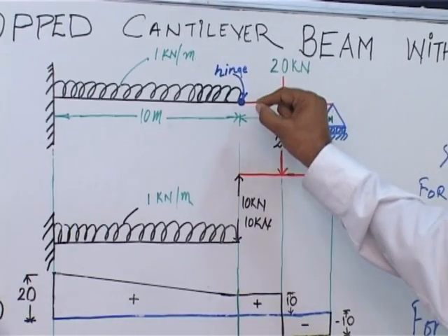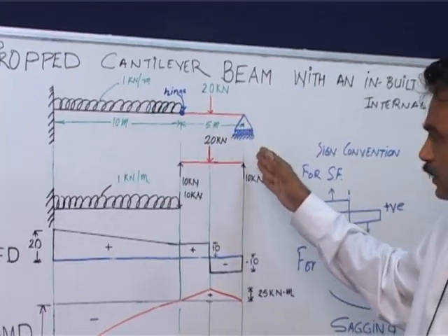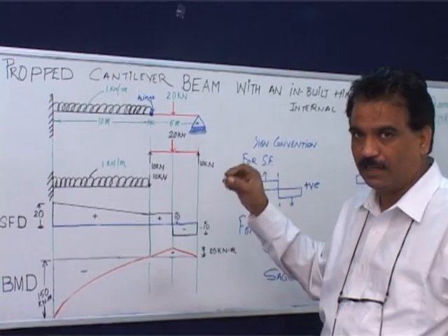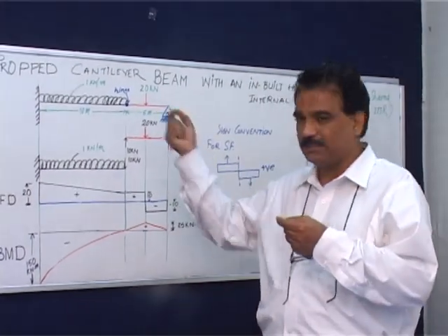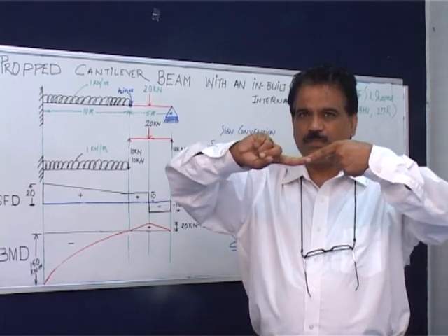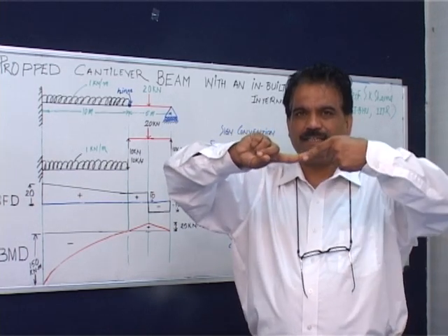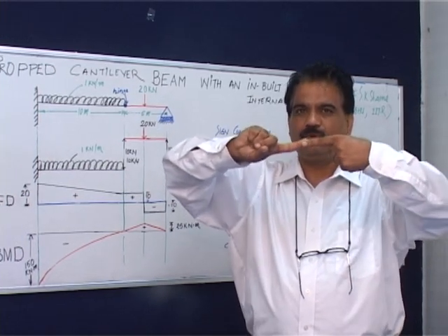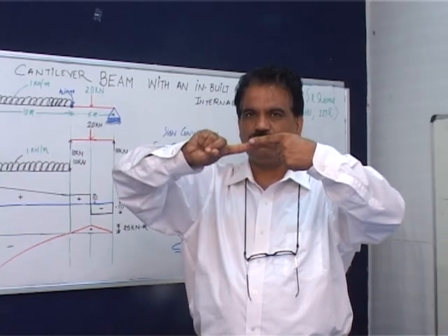Where this hinge is in the middle, the hinge will divide this beam into 2 portions, not just mechanically but also by the action that the hinge is introducing at this beam part. Let me just tell you how. For example, if we are joining 2 parts of the beam at a hinge, then possible actions are here. It does not resist a moment. But what it does, it resists a shear force. For example, if you want to just take it away, it will not move.